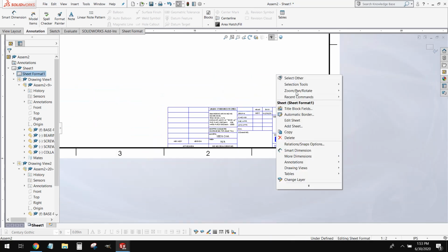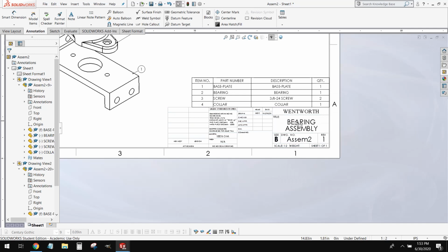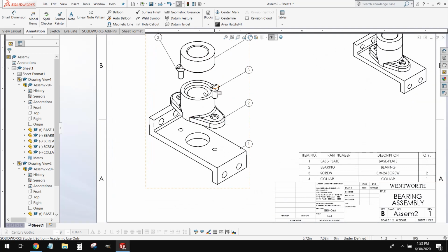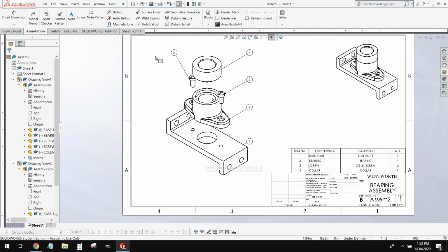So what we can do is go back to our full sheet. And this is typically all we would have on an assembly drawing. They're not usually very complex. We may include some notes in here. If we have to use a certain torque setting to screw these screws in, if we have to apply an adhesive or a solder to any of the components, anything like that, we could put in a notes section.